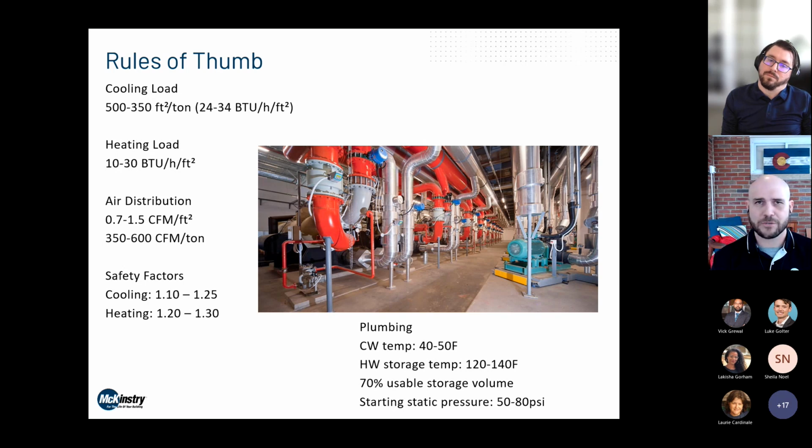And building water pressures of 50 to 80 psi is pretty good. 80, I think, is where code requires a pressure reducing valve if your building is above 80 psi. So, yeah, some places, I think in Florida, even, you're lucky to have maybe 30 or 35 psi water pressure from the street.